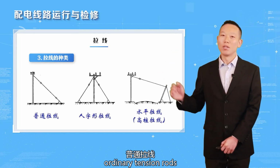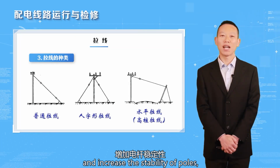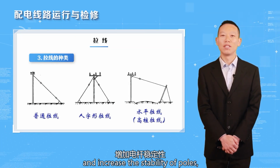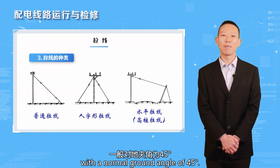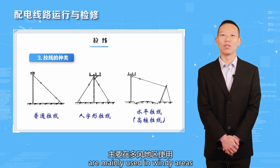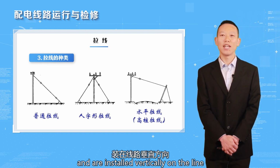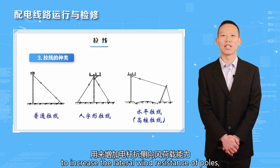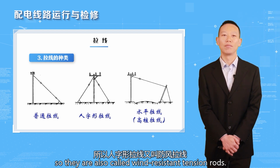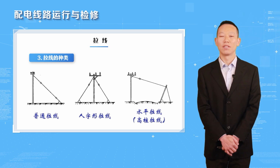Ordinary tension rods are mainly used to balance unidirectional forces and increase the stability of pulls with a normal ground angle of 45 degrees. Zigzag tension rods are mainly used in windy areas and are installed vertically on the line to increase the lateral wind resistance of pulls. So they are also called wind-resistant tension rods.